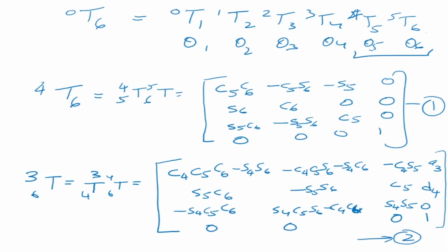So what we did is we first multiplied this, then we multiplied with this. You'll understand why. Now, so this is one set. T3 to 6 is one set that we have multiplied. The other set that we are multiplying is T1 to 3. So we just take those 1 to 3 matrices and multiply them out.